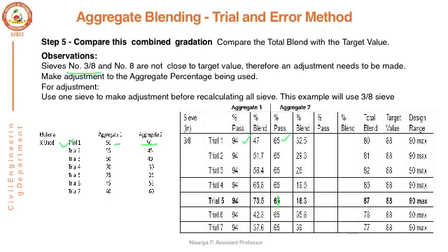So how do you obtain the percentage blend? In trial 1 it is 50-50, so 50 percent of 94 is 47. In trial 2, aggregate 55 percent of 94. Trial 3, 60 percent of 94. Similarly, we have to calculate for all other trials. Now for aggregate 2, the percentage pass is 65 percent. So all these values have to be multiplied with the proportions that I have considered for aggregate 2, that is 50, 45, 40, 30, 25, 55 and 60 percent respectively.